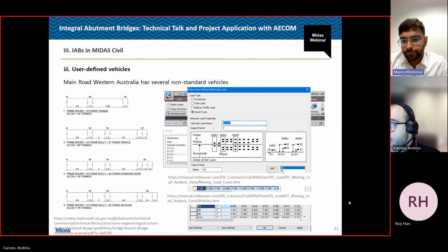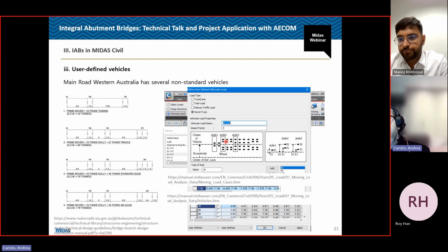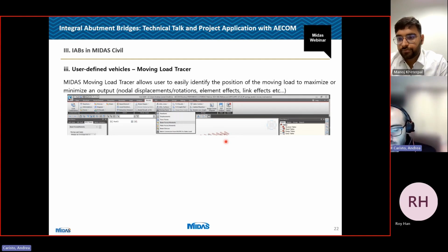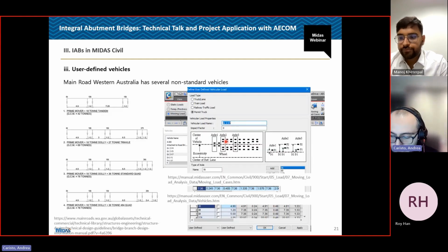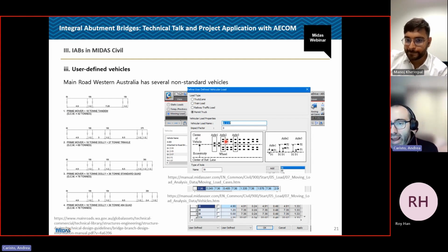Also, I can see the impact factor is given as 0. So you considered them after, in the load combination? Yeah, so this is due to the specification of the project. Basically, without going into too much detail of the Australian standards and the bridge manual, these vehicles have different impact factors, dynamic factors let's say, based on whether they're going to be supervised or unsupervised vehicles.